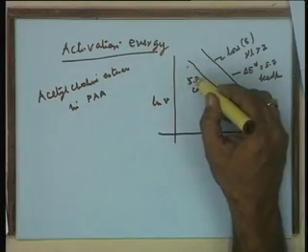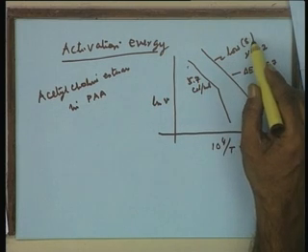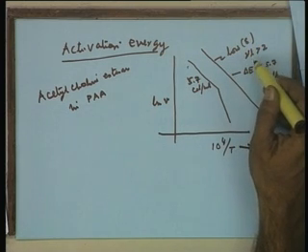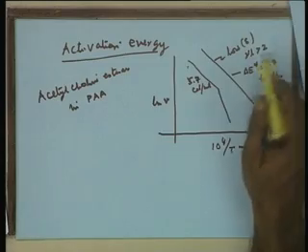The rate of reaction being much higher, diffusion became limiting, and so the activation energy behavior was almost similar to that at low substrate and high gamma L, which is the established parameter for diffusional limitation.